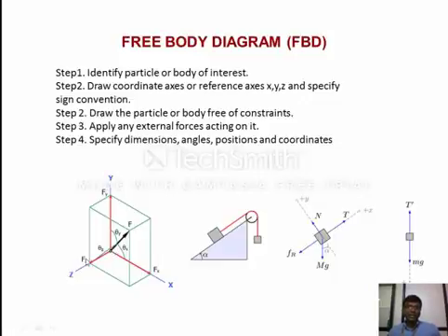That means negative. You have to use it. In the sign convention, if the force is along the direction of x, y, z, then it is positive. If it is against that, then it is negative. Similarly, clockwise is considered negative. If the moment creates a clockwise rotation, it is negative. If it is opposite, counterclockwise, that is assumed positive. This is the sign convention, and you have to be very careful with it. You can use any kind of sign convention, whether right hand rule or left hand rule, but you have to stick to it because you cannot mix the sign convention.